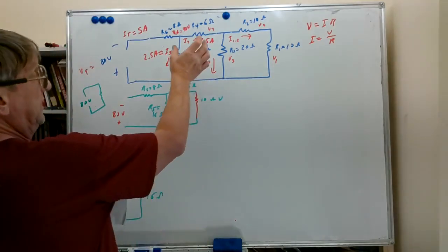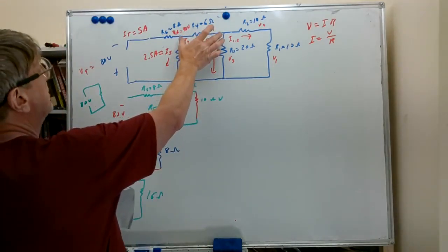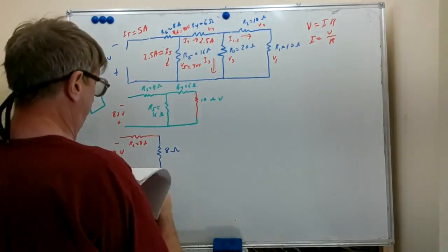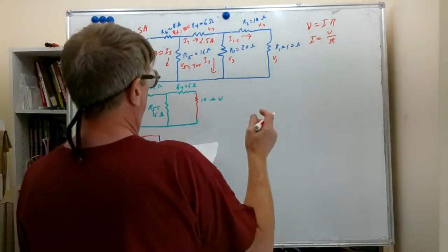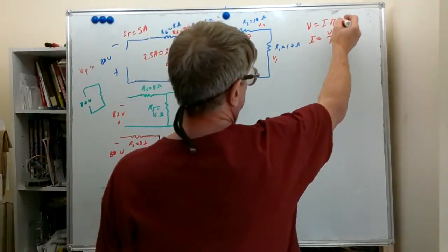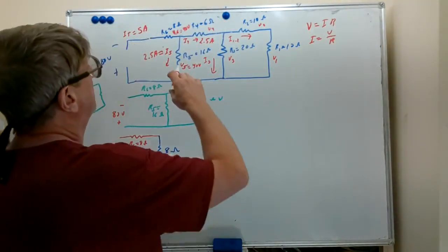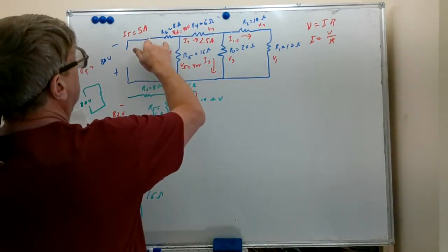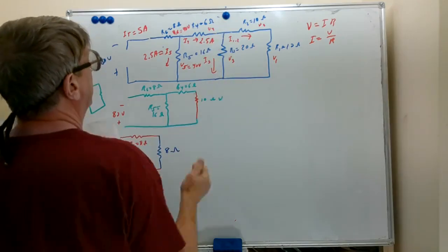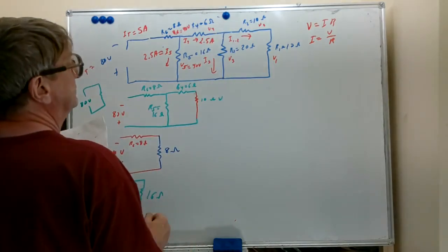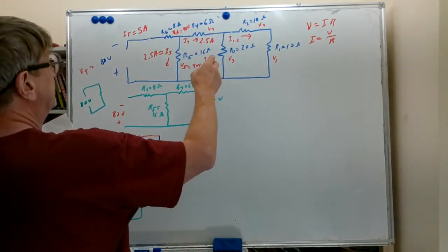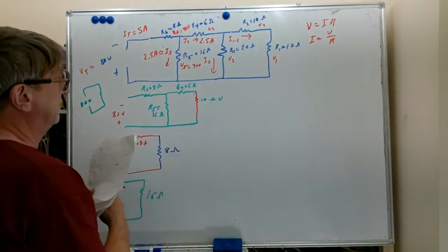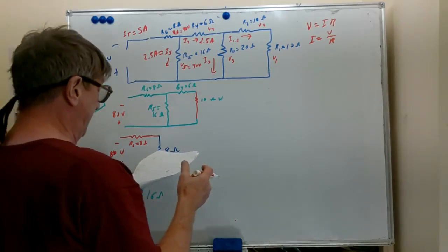Well, if we can have the voltage here, we can take 80 minus 40 minus whatever that is, it'll give us the voltage here. So let's look at our voltage formula again. And our voltage summation formula for a series circuit, we'd like to find the voltage of this plus this plus this. But let's first calculate the voltage for R4, because we're going to need it to do that.